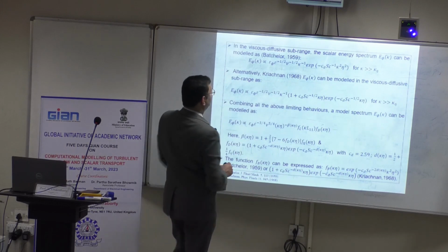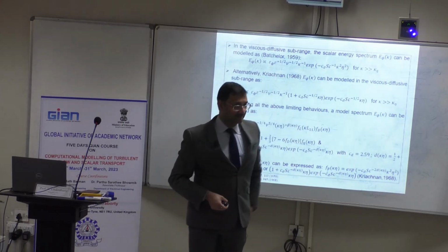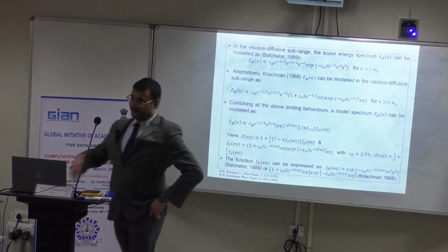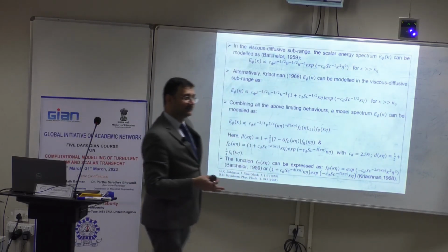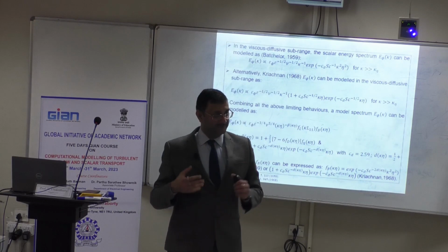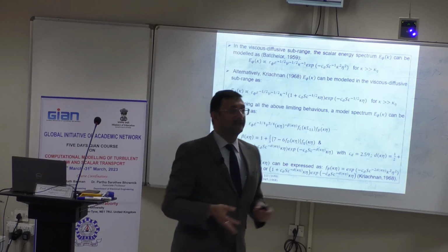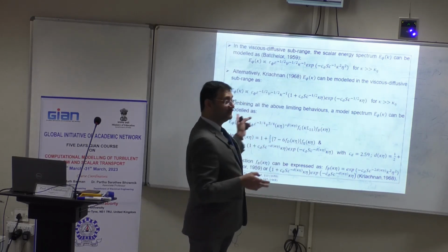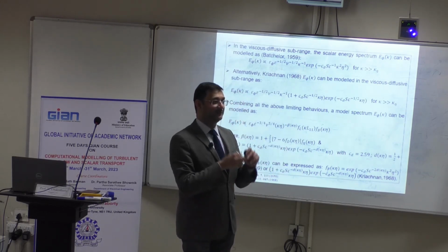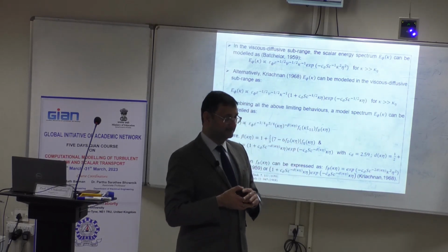The other thing I want you to note is that kinematic viscosity explicitly appears in this picture. So if somebody says the turbulent process effectively gives rise to things which are only flow properties, that's not necessarily the case. Essentially, when it comes to turbulent mixing, the molecular property still continues to play an important role. And you can perhaps appreciate from the fact that depending upon the Schmidt number, which is a molecular property of the fluid, the scalar spectrum behavior is going to be very different. Clear?